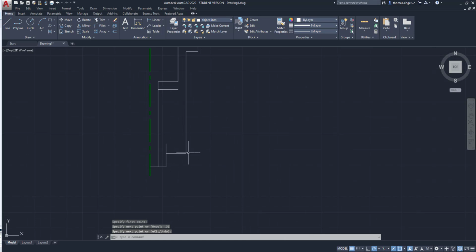So now it looks all messed up in my drawing. So as we magnify here, this looks all messed up. But what this is telling me is that I need a line that's going to come down to here for the outside wall that's going to stop at that horizontal line that I just created, that construction line. That line is going to move all the way across to that half-inch hole. So now it looks like this. But we're not done. We need to erase that little construction line of the 0.31, and we need to trim this section out of that line. So we're going to pick trim, pick the upper horizontal line, the lower horizontal line, right mouse click, and trim.